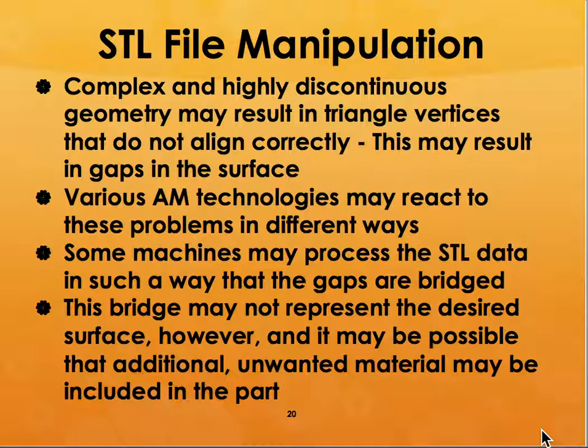But sometimes some of these machines will process the STL data in such a way that the gaps are bridged, but in some cases you may not have proper material put in there, or you don't want unwanted material to be put in there, which will make it hard for you to lay down that layer. So if your layer is not flat or the right size and shape, then you are going to have issues.